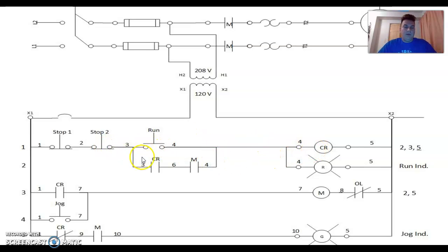All right. I don't want to say overkill, but there are things done here for certain reasons to ensure that if the motor's running, things will seal in and keep it running. So we have 2 stop buttons, stop 1, stop 2. Either one of those obviously will prevent the motor from running, but you could still jog it. There are modifications that I like to make to this circuit in shop, where I have you put the stop button so that the jog button won't work as well. Unfortunately, we didn't get to that, but look forward to it next semester.